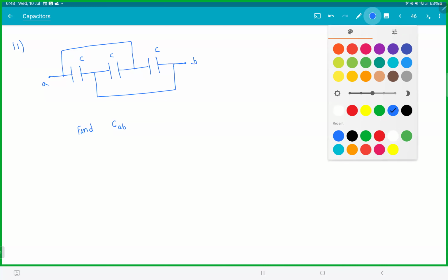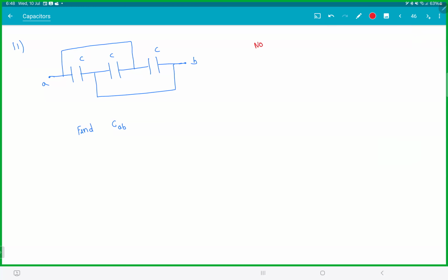So let me teach you a method here. This thing we can call the numbering method, nodal analysis. So what we do in this, step 1, identify the number of nodes and check for nodes with the same potential.